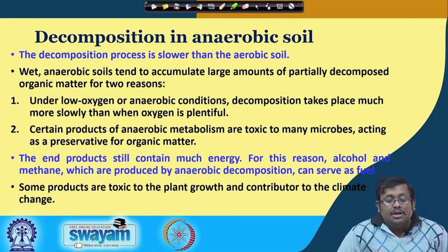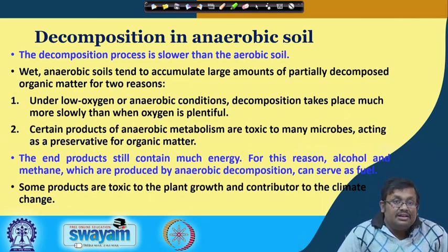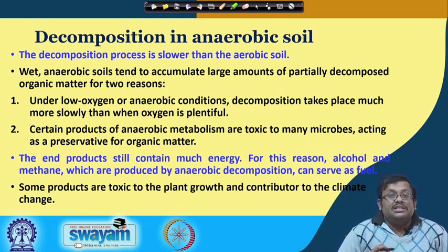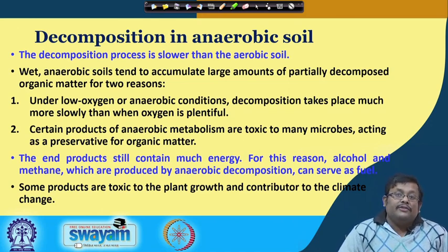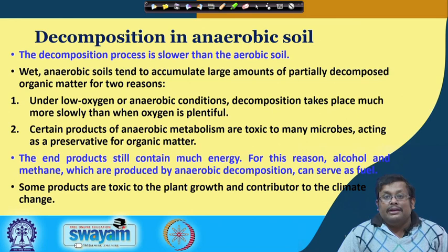Obviously, this decomposition process is slower than that of aerobic soil, and generally you can see this type of decomposition in wet and anaerobic conditions. Because of this slow decomposition, wet and anaerobic soil tends to accumulate a large amount of partially decomposed organic matter, mainly for two reasons: under low oxygen anaerobic conditions, decomposition takes place much more slowly than when oxygen is plentiful, and secondly, certain products of anaerobic metabolism are toxic to many microbes, acting as a preservative for organic matter.